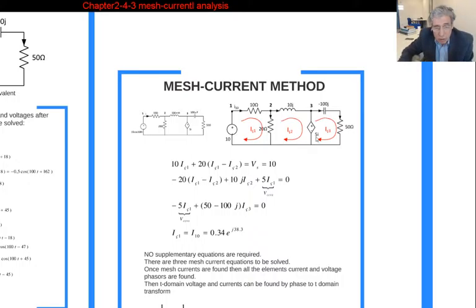According to it, this dependent source voltage is equal to 5 times E. So I write 5 and then this E. This E is this resistor current, which is also the same as this loop current, so I've replaced it with IC1. So what we wrote here is the Kirchhoff voltage law equation for the second mesh.